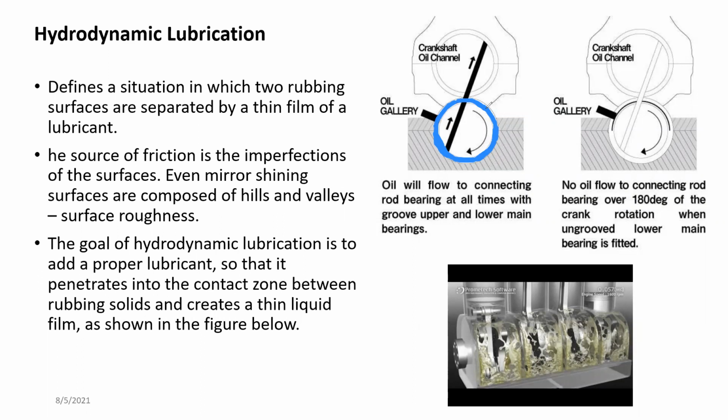So by using the lubrication system, it actually reduces the engine's weight drastically. If you needed ball bearing or roller bearing type lubrication, it's going to add additional components, not to mention those components will wear out. So that is not the best solution. That's why most of these vehicles have this hydrodynamic lubrication system.